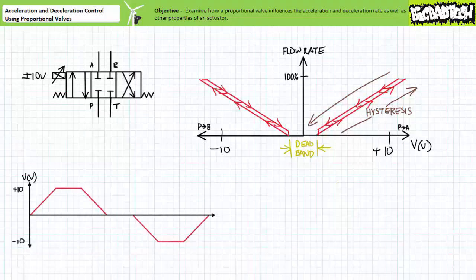As mentioned in the above referenced lecture, the pressure shock associated with traditional fully closed or fully open directional control valves can be mitigated by smoothly ramping applied voltage up or down over time delivered to a proportional valve, thereby slowly opening or closing the valve and suppressing the pressure shock. This progressive increase or decrease in flow rate also directly lends itself to the controlled acceleration and deceleration of the applied load. When applied voltage is plotted with respect to time, note this actuator would be performing two separate actions, an extension phase followed by a retraction phase.